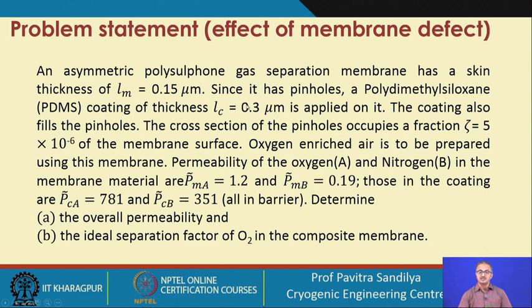Now because this thickness is more than the thickness of the particular membrane, this particular coating will also offer its resistance to the mass flux. But we have to do it to save the membrane, so that we do not have to go for a new membrane. So initially we may use such kind of coating to cover up any kind of pinhole.